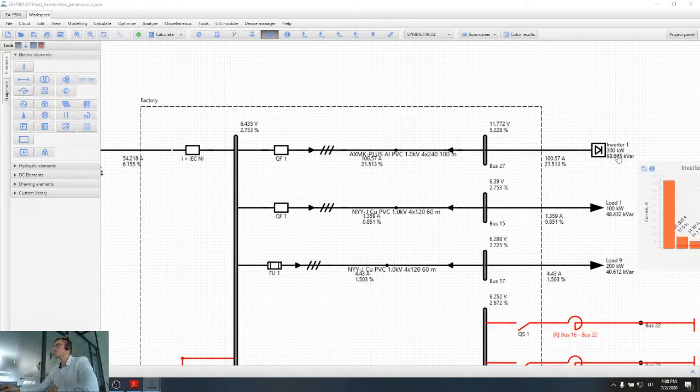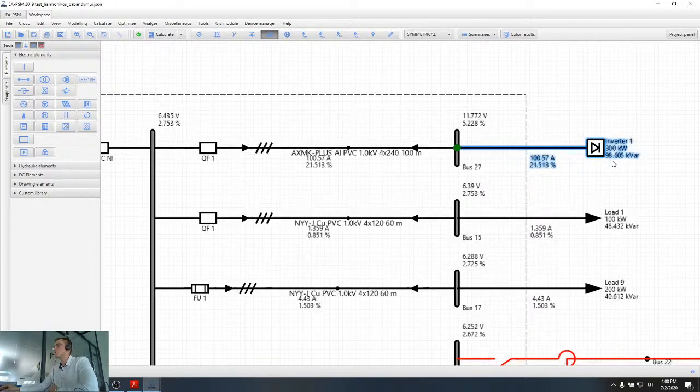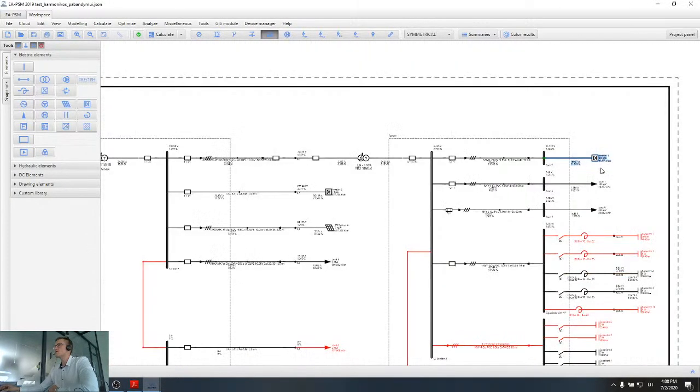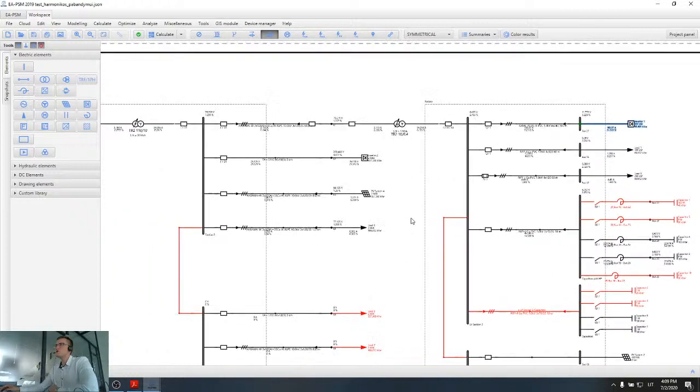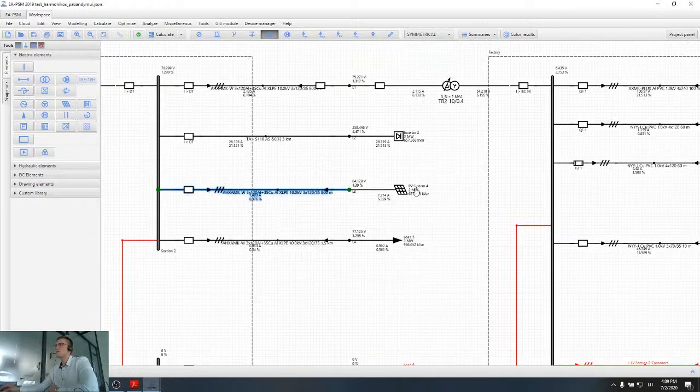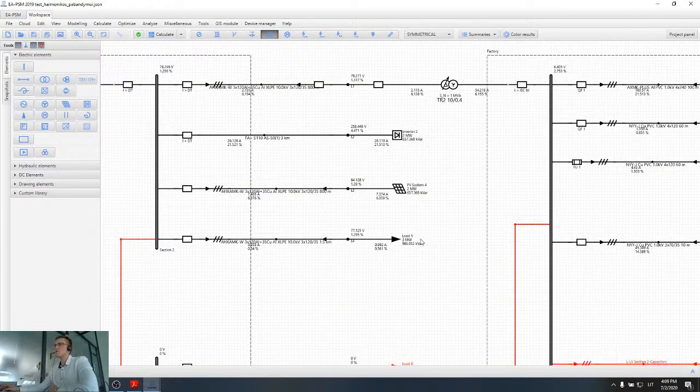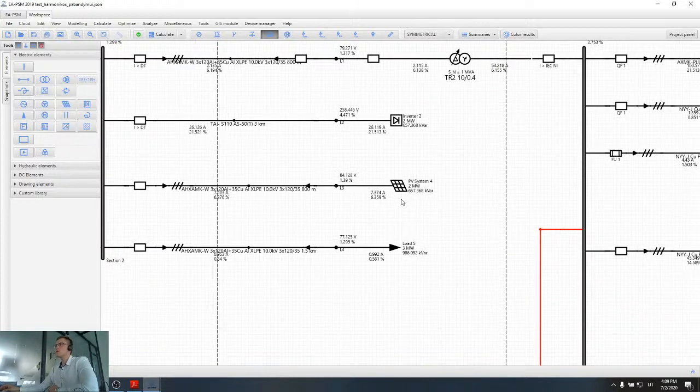So the calculation algorithm to analyze current harmonics is enough to analyze industrial networks. In other cases, like if we have wind turbines, which might be voltage harmonic sources, then yes, we might need another type of calculation. But again, if you have measurements of the currents created by the wind turbine, you can use those calculations to also do wind turbine calculations in the software.